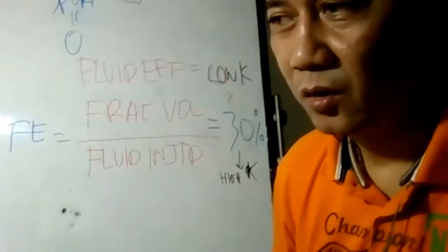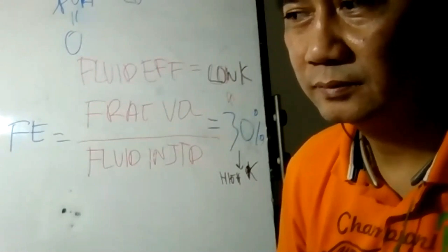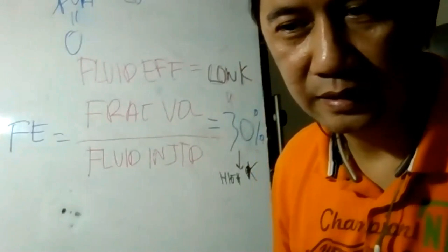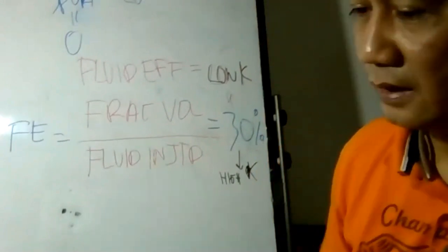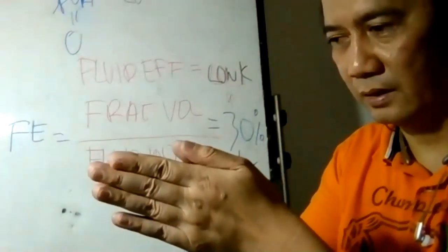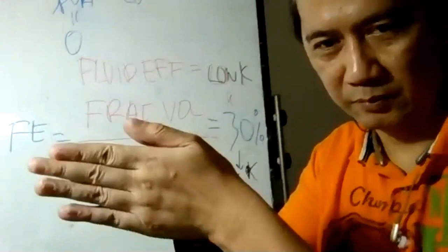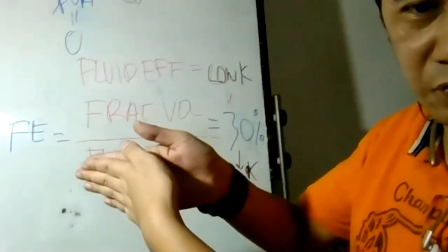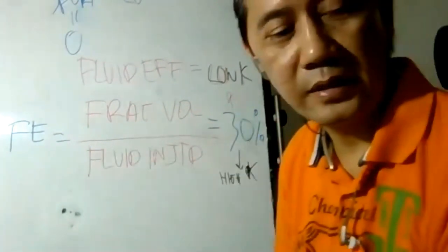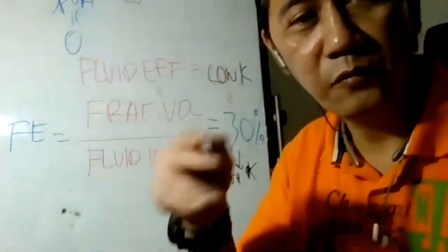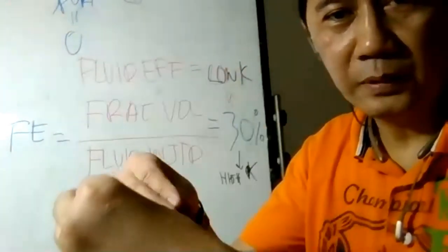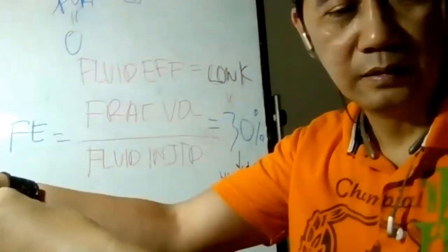All right. So I think I have a simulation, and I'll share it with you later. But again, HiWAY is this: if you're pumping a frac job, you are pumping fluids and proppant, and all this fluid and proppant will fill up your frac volume here. With HiWAY it is different. With HiWAY you are pumping proppant and fiber. You are pumping proppant, fiber, proppant, fiber. So what does it mean?